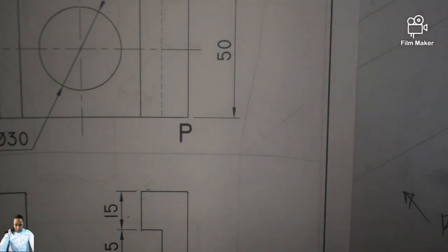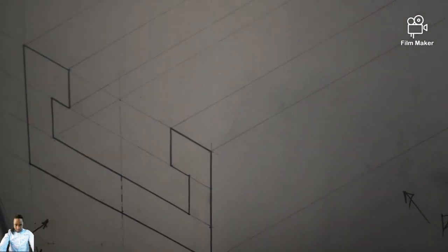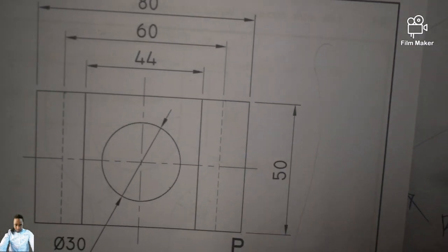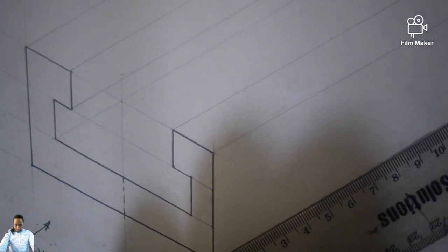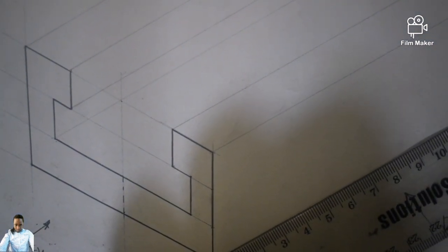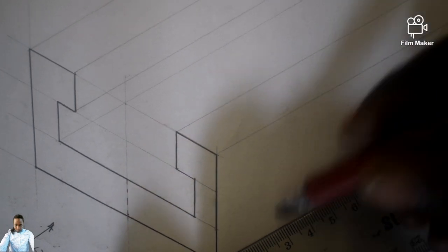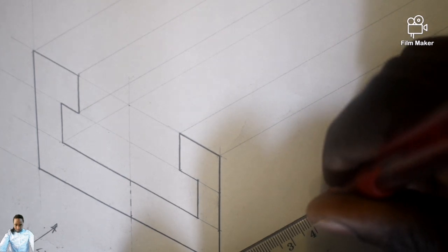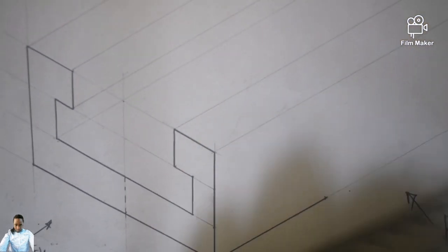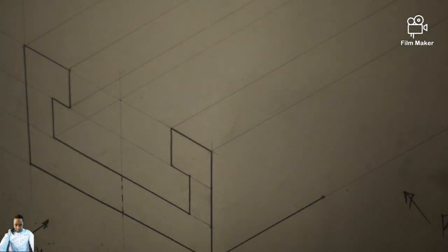top view, they will always share the same width. Which means from here till there is supposed to be 50 millimeter. So I can come from point P, from here, there you go, it's my 50. I can even draw it dark, you understand? There's my 50 millimeter.